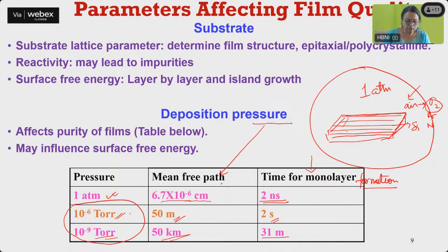So we will be using this kind of vacuum because the first thing is that the mean free path is increasing. How is the mean free path important? Now this is my substrate. We again go back to thermal evaporation, if you remember from that day. I have a coil, I am passing some current through this, and the material which I want to evaporate, I am putting in some crucible. Say I am evaporating gold or silver, and I am passing the current, so it will get evaporated and atoms will come and sit here.